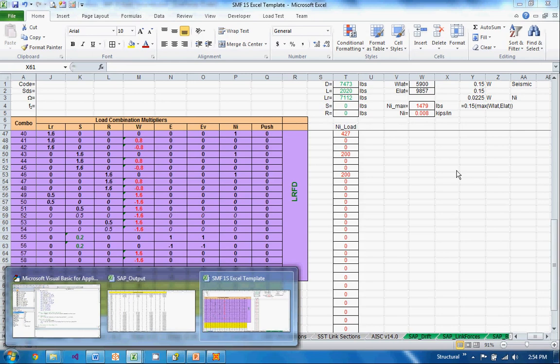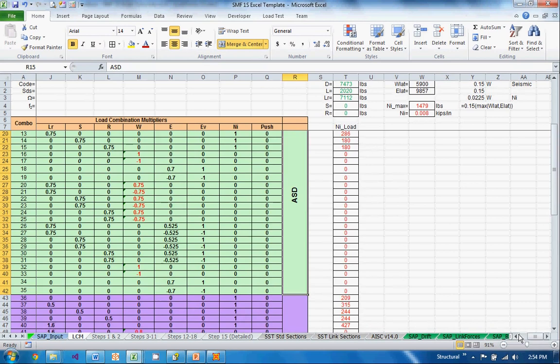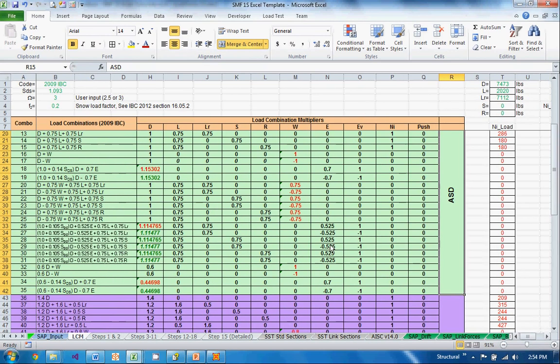So the bearing pressure, 2 KSF, 3 KSF, 4 KSF, those are still in allowable stress. What I'm talking about is when you're doing the foundation design, the bearing pressure check, the engineer does it. Those ones are ASD combos. They only use ASD combos.